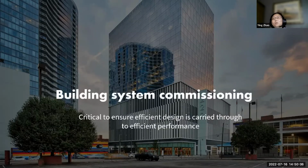Another thing we will talk about. We already talked about the design phase, how to make the building more efficient, and there are some very critical other steps and measures that are not in the design phase, but in the construction or operation phase, to make sure your design is actually well implemented and effective. So one thing is building system commissioning, which is critical to ensure efficient design is carried through to efficient building performance.